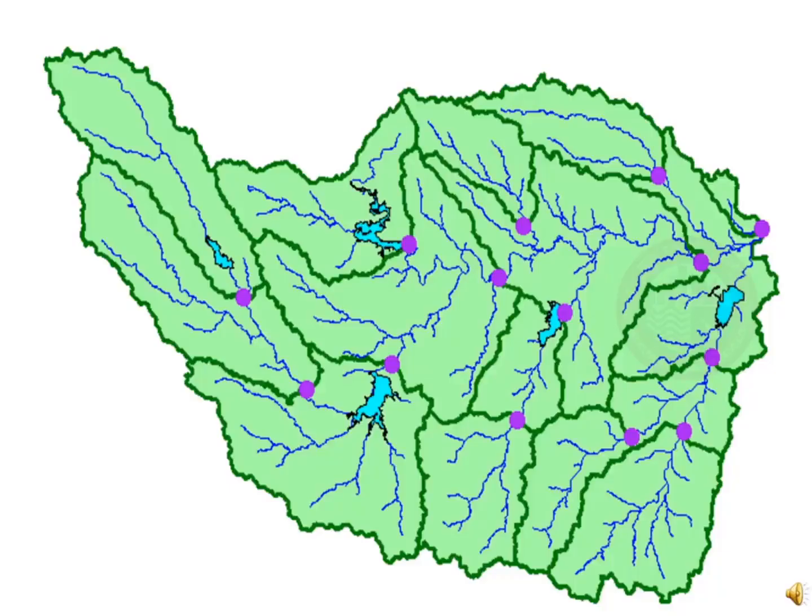Watershed area analysis. This is the localized catchment area of a watershed or subwatershed with drainage network. This drainage network depends on terrain conditions. This watershed GIS map will be very helpful for construction of check dams, water retaining structures or groundwater recharging structures, or for local farmers for afforestation or for irrigation, etc.